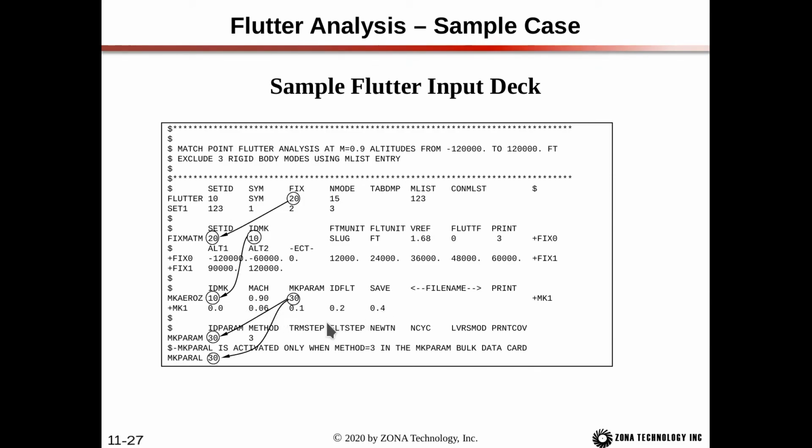Meanwhile, we have the MK param card to define parameters for the Flutter analysis, and we have method equals 3 in the MK param, which activates the frequency domain linearized Euler solver. So the aerodynamics are computed directly in the frequency domain.